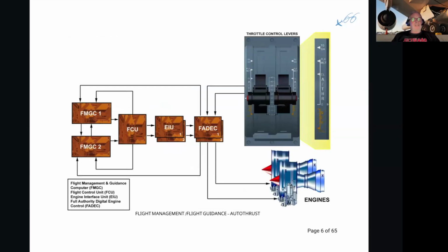In terms of auto thrust, we already said the engines are managed by computers, by a FADEC system, a full authority digital engine control. So they spool up, they increase and reduce in power, which means the fuel control unit will get more or less fuel depending on the demand on it, and the demand depends on what is requested from the current situation.